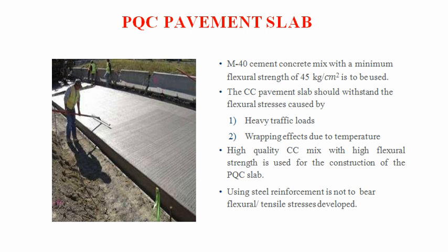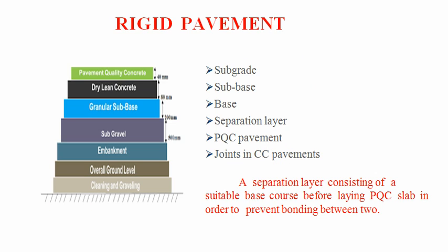The cement concrete pavement slab should withstand the flexural stresses caused by heavy traffic and the warping effects due to temperature. A high quality cement concrete mix with high flexural strength is used in order to construct the pavement quality concrete slabs. So when steel reinforcement is not used to bear the flexural or tensile stresses developed, we can go with the PQC slabs.